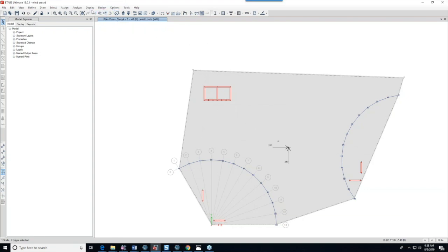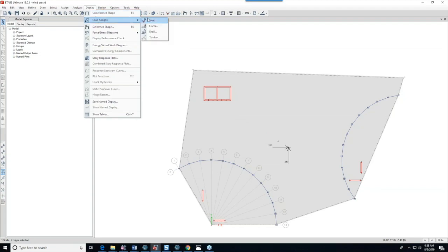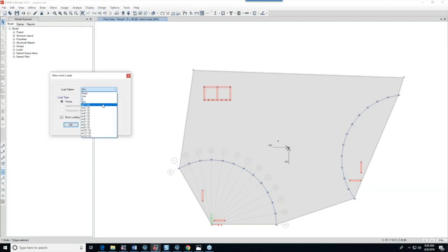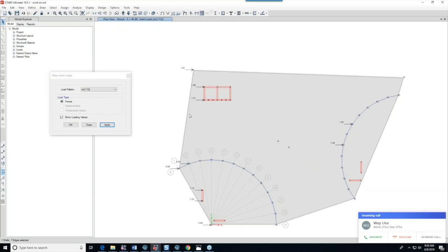And if I were to display the joint load assignments for the wind load, you can see that the program struggles a bit to find joints to assign. It will find these easily, but it may not be the location that's best suited for applying these loads. Yes, it's distributing the loads out. These are wind loads, but you can have a little better control over how the wind loads get assigned by introducing some other joint elements in here. I apologize.